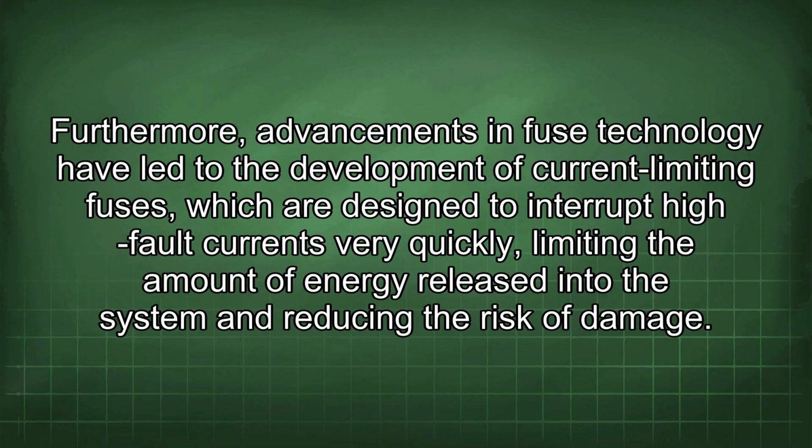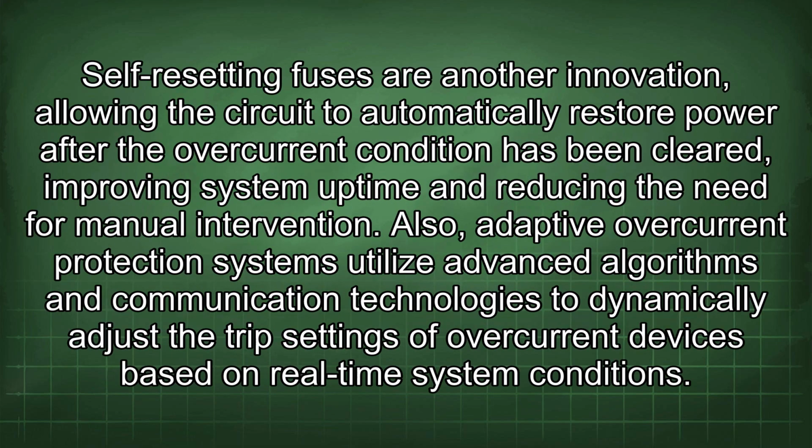Furthermore, advancements in fuse technology have led to the development of current-limiting fuses, which are designed to interrupt high fault currents very quickly, limiting the amount of energy released into the system and reducing the risk of damage. Self-resetting fuses are another innovation, allowing the circuit to automatically restore power after the overcurrent condition has been cleared, improving system uptime and reducing the need for manual intervention.